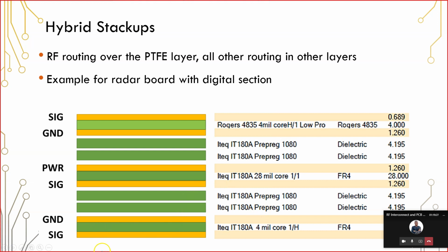But the high speed signals, maybe like Ethernet or USB or something like this, should be on this bottom signal layer. Now, if you had to support a lot of high-speed signals, you may want to actually re-engineer this so that you have the thick core layer, and then you have a thin layer between the ground on L2 and then the power on L3. And so if you make this region much thinner and then have the thick core in the middle, that's actually beneficial for power integrity.